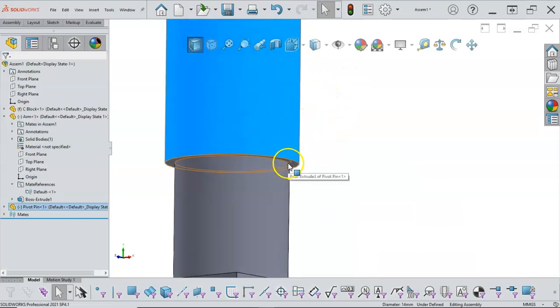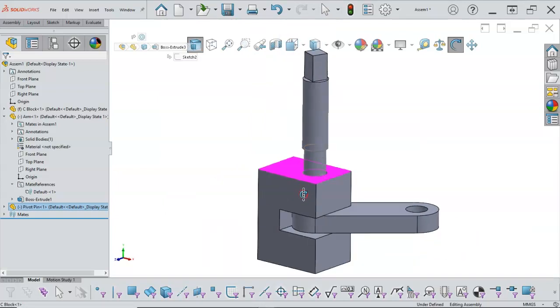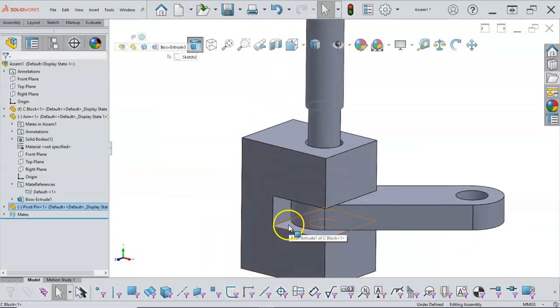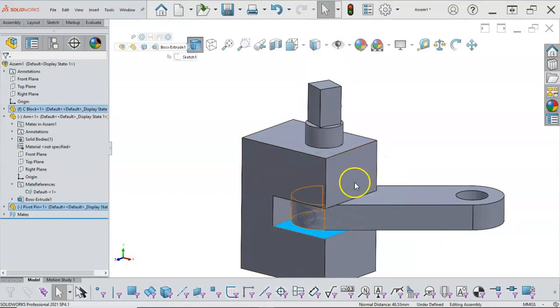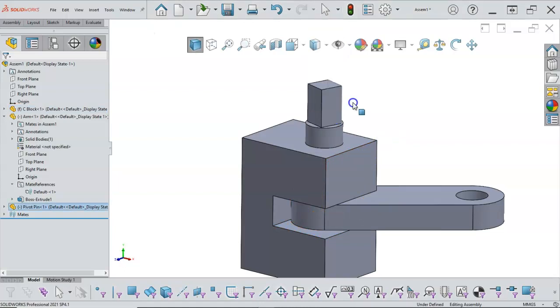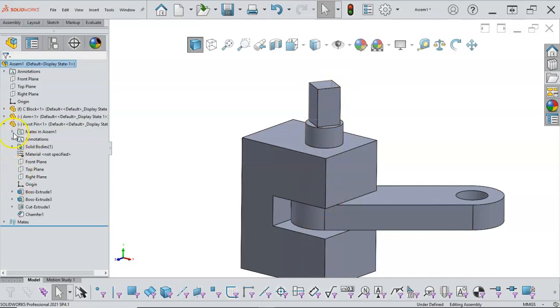We didn't put a relief in here, so there ought to be a partial thread where this is not going to quite seat onto the base, and we didn't continue the 14 millimeter. So those are minor mechanical issues that we might want to consider resolving. This still has the ability to turn, so I bypassed, or I missed the little pop-up that said lock rotation.